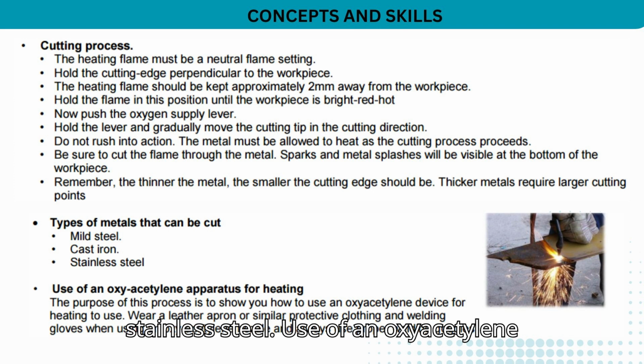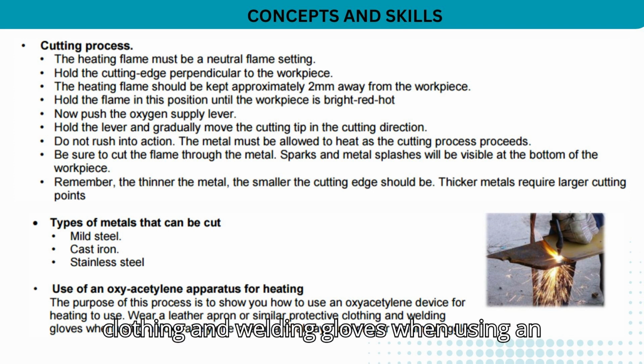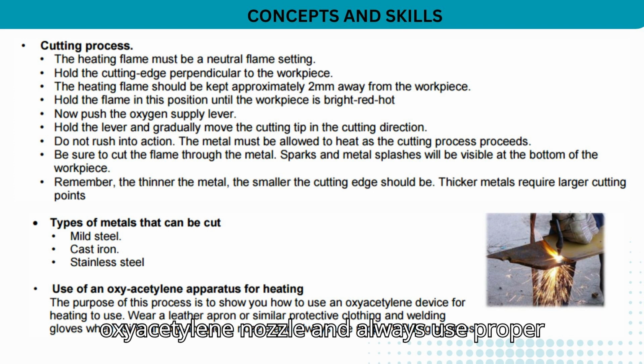Use of an oxyacetylene apparatus for heating. The purpose of this process is to show you how to use an oxyacetylene device for heating. Wear a leather apron or similar protective clothing and welding gloves when using an oxyacetylene nozzle, and always use proper welding goggles.